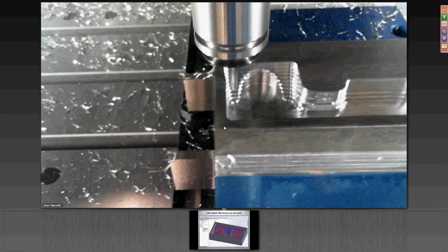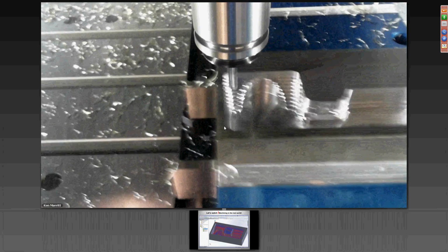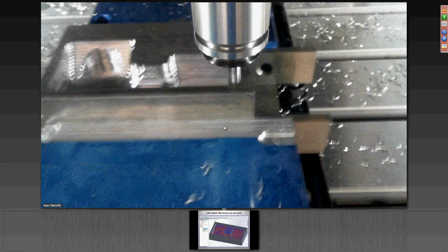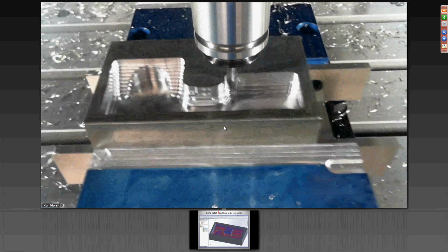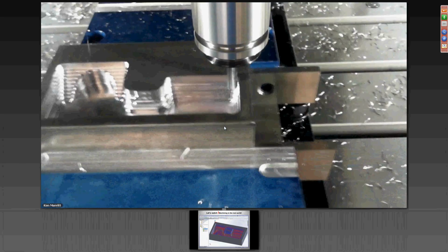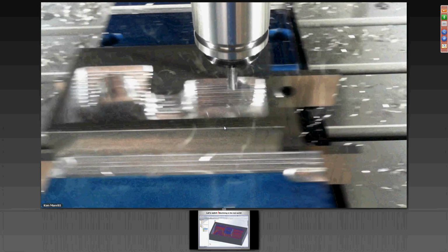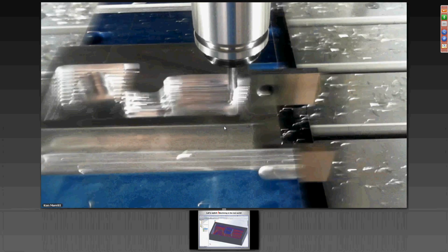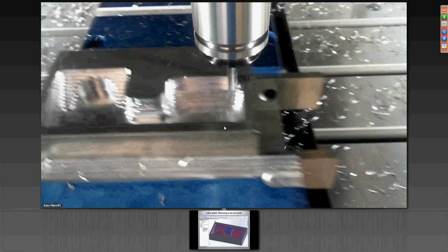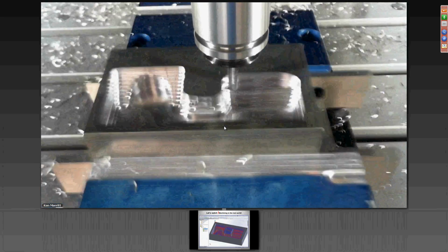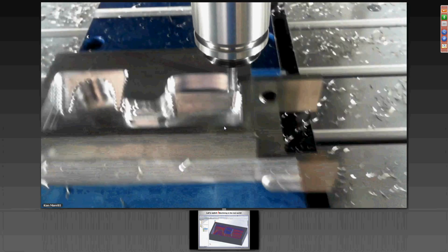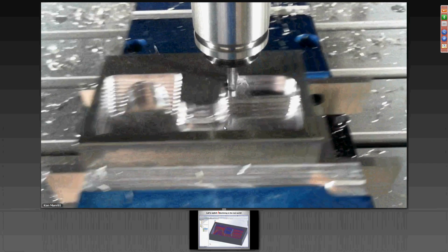path is that if the roughing path leaves an inconsistent staircase, then our finish tool would see uneven loading and unloading during its cut time. This would obviously cause issues with our surface finish. As you're going to see at the end of this cut, we're not going to do a semi-finish on this. We're just going to go straight to the ball tools, and you're going to see a very, very nice surface finish at the conclusion of this operation.